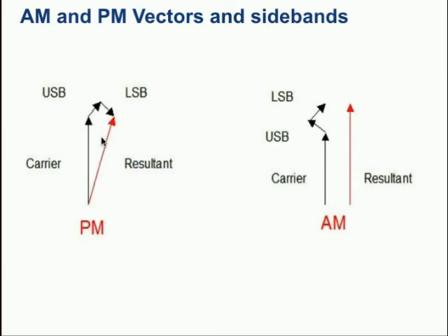The noise in the device is characterized purely by its noise figure. Now, it is okay to do this, but it's more complex than just the published noise figure of the device, the noise figure that would be the parameter to use in the case of a low-level amplifier, because there's another completely different noise mechanism where the phase of a high-level carrier can be modulated by noise.